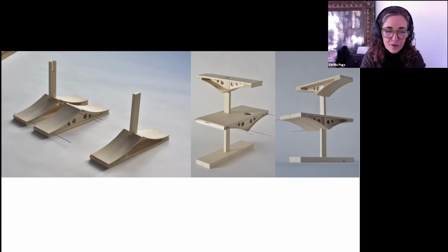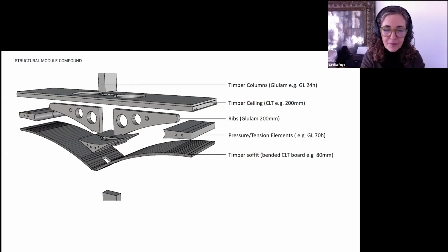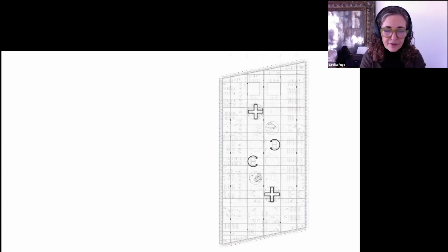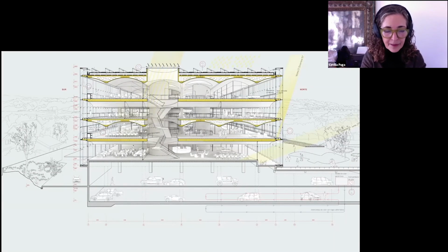This construction system was developed in collaboration with the Swiss wood construction company Blumen-Lehmann, who developed the construction methodology and supported the construction process with the development of parts, technical accompaniment, a structural prototype, and eventually the construction of the building. The building has a trapezoidal floor plan and contains 4 main floors in a wooden structure and 2 in reinforced concrete in the basement. The supporting structure consists of a system of columns and wooden slabs covering a span of 18 meters.